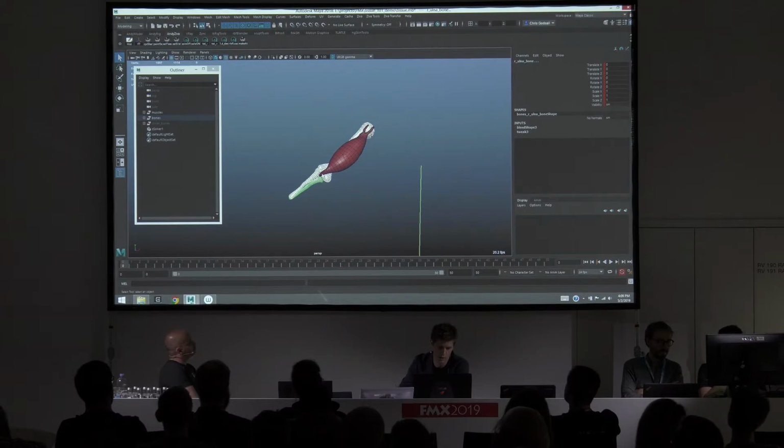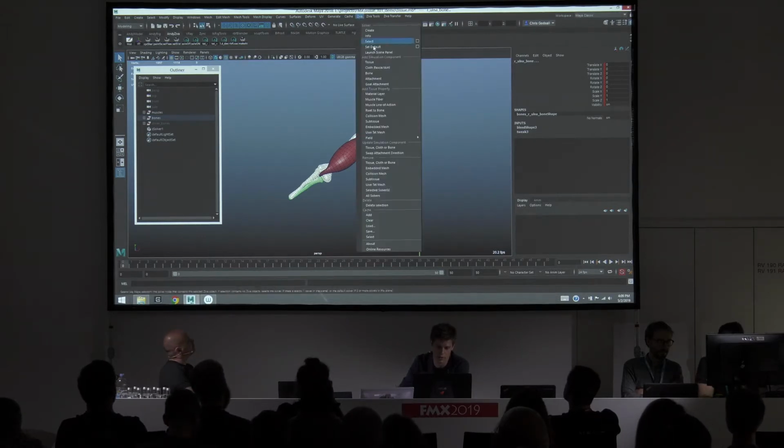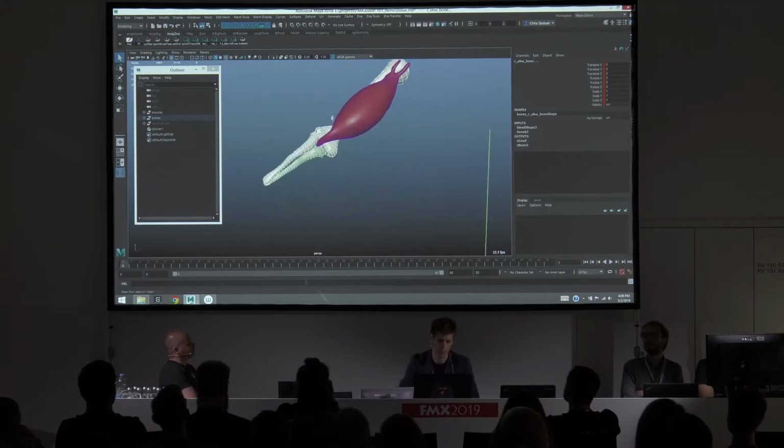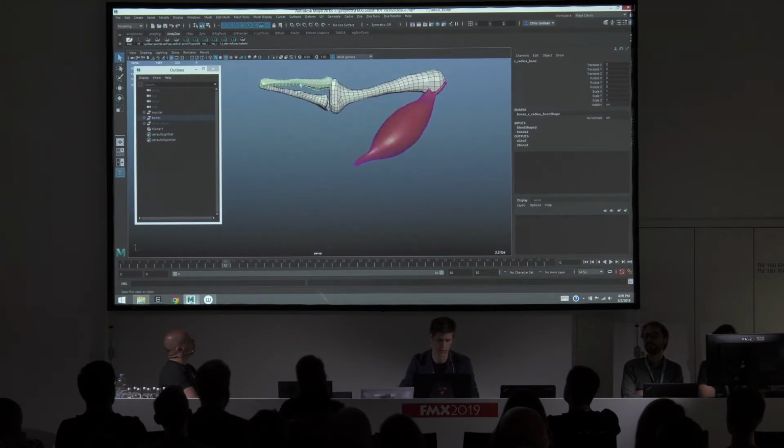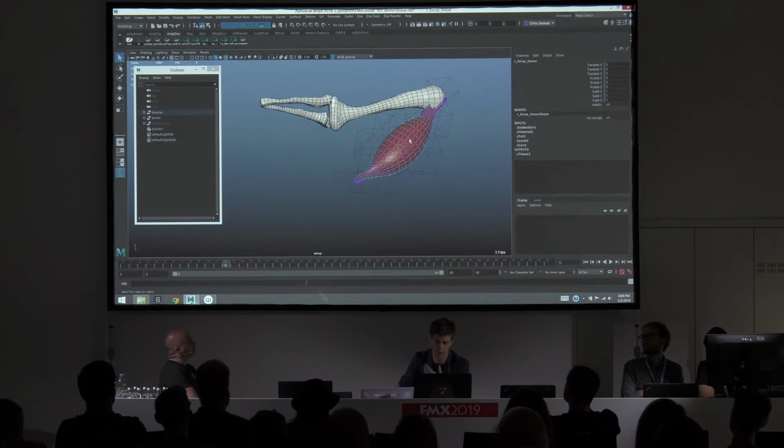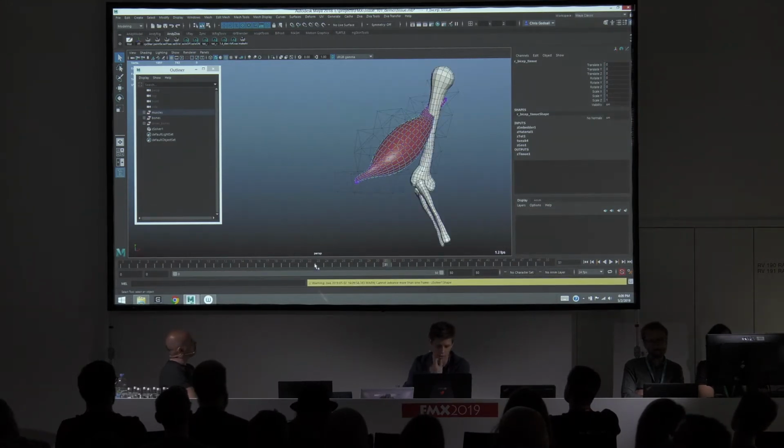So these objects here, I'm going to convert to Ziva bone objects. Under the Ziva menu, I can come down to add simulation component bone, and you'll see that we got some draw stuff here. When I move this around, you're going to see these things follow along. You notice that the tissue didn't update because it's a physical solve. It's dependent on the frame before, so you can't jump randomly in the timeline.